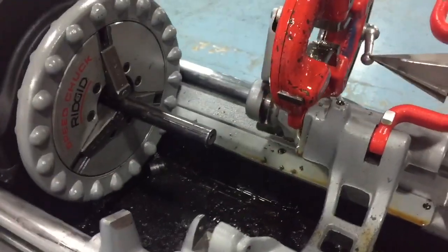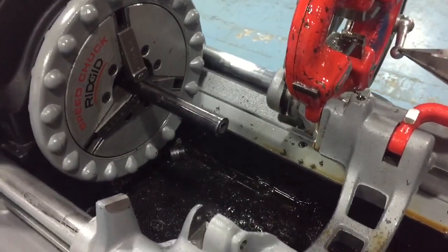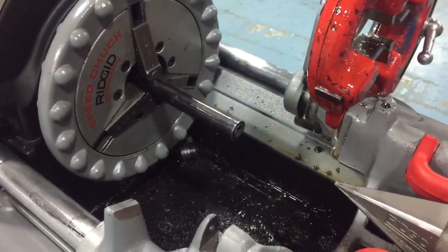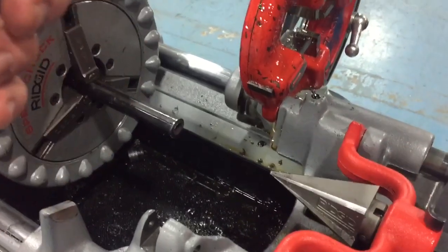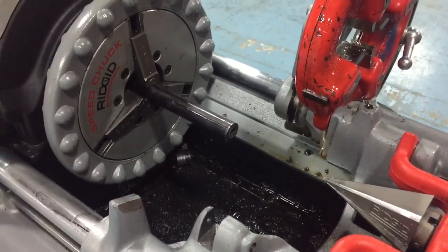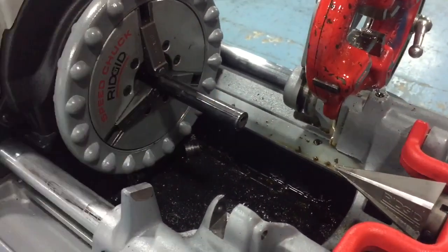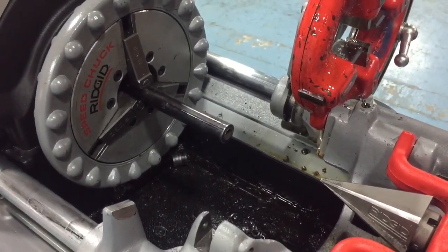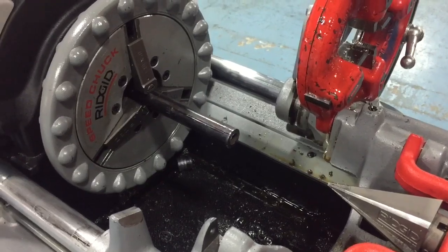So to speed things up, I'd recommend, rather than just flipping it around and threading the other side, we start all over and start cutting and making our next pipe. So we want to ream, thread, and cut this, and then once we have all of our joints cut, we can take our length out of the machine and do the other side of each of the other pieces of pipe, ream them and thread them.